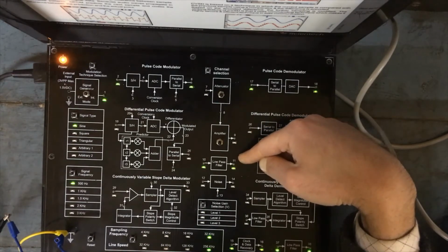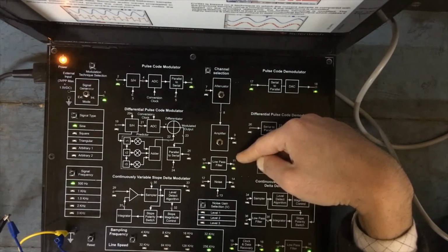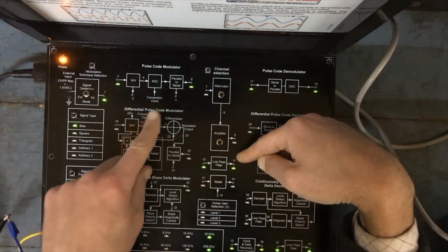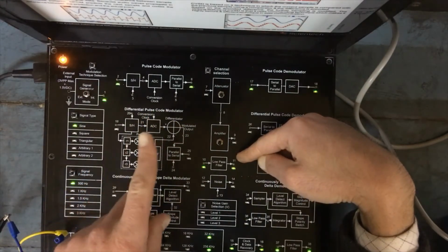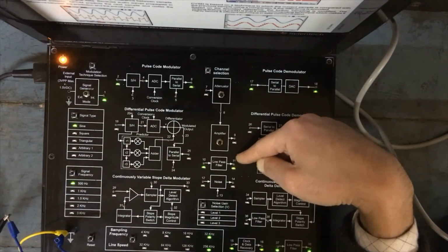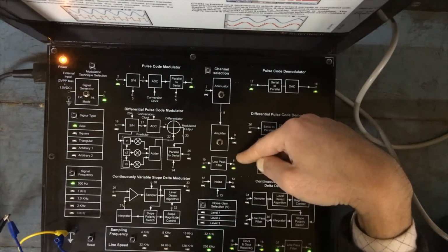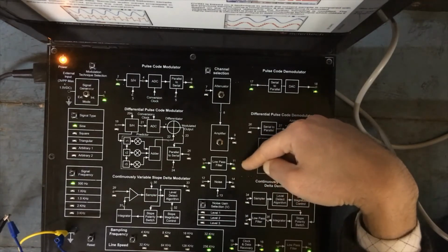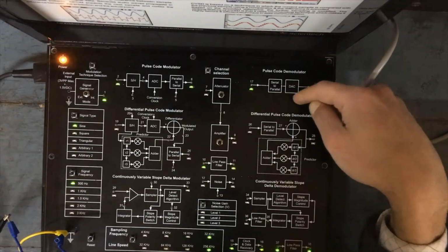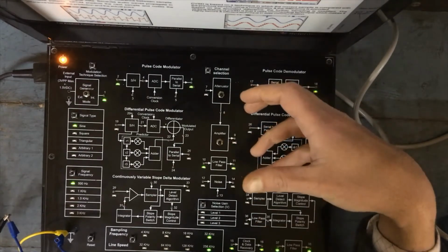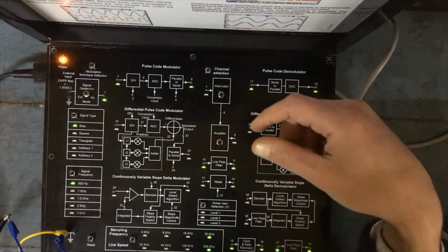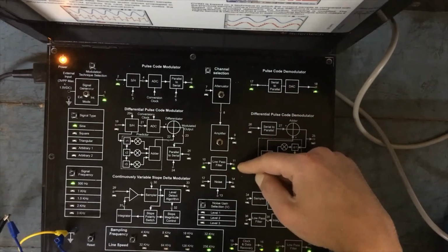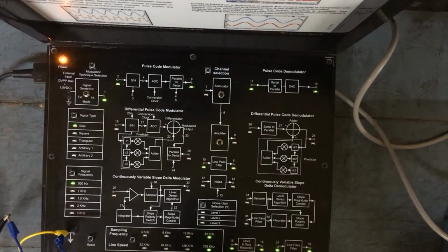If you use the low pass filter model of the channel, then of course the higher frequencies are lost. Obviously over here the bits are ones and zeros, which are perfectly square waves, so the higher frequencies need to be added to the signal again, because if that is not done, the pulse code demodulator will not be able to differentiate between a digital 1 and a 0. So that is done using this clock and data recovery.